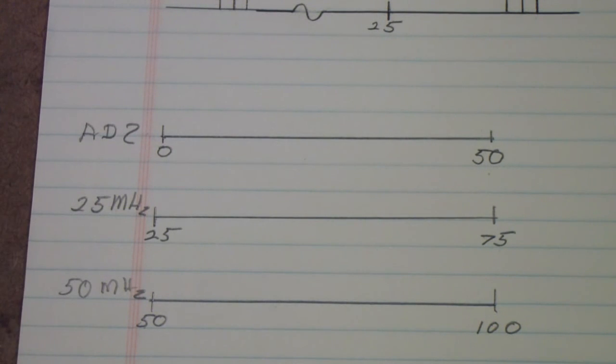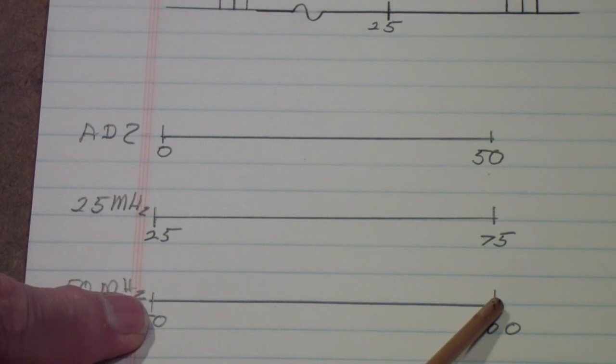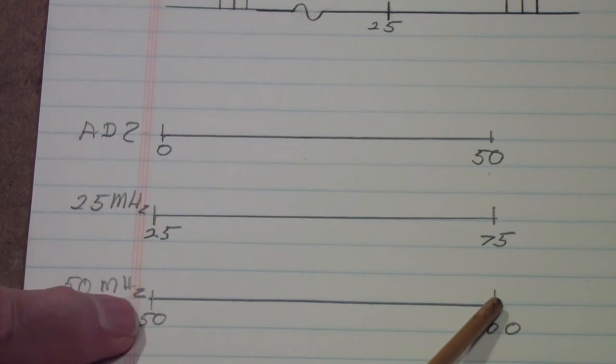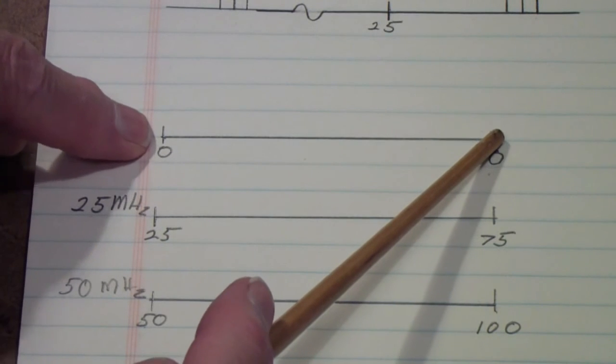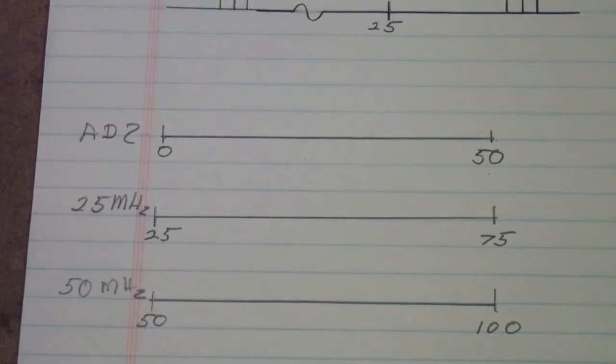Not only will it be a useful tool in the laboratory, but it also is a useful learning tool in teaching students the uses of mixers, not just to move one frequency, but to translate an entire frequency band from its fundamental down to some translated frequency range that's within the range of a test instrument like the Analog Discovery.